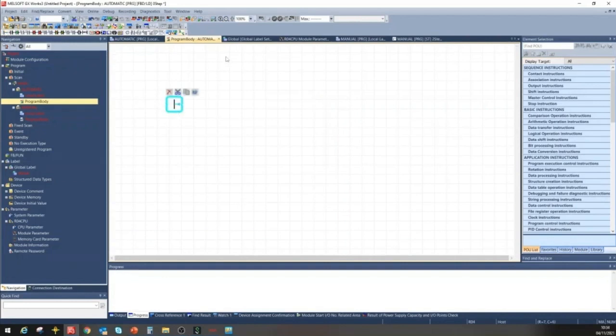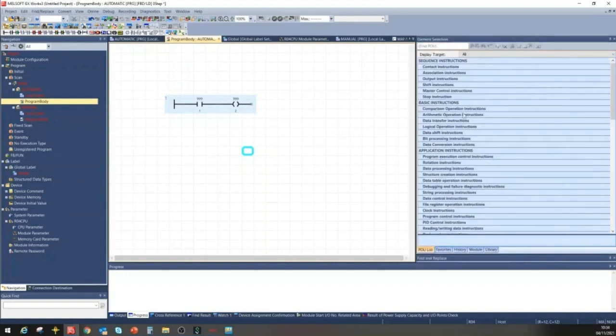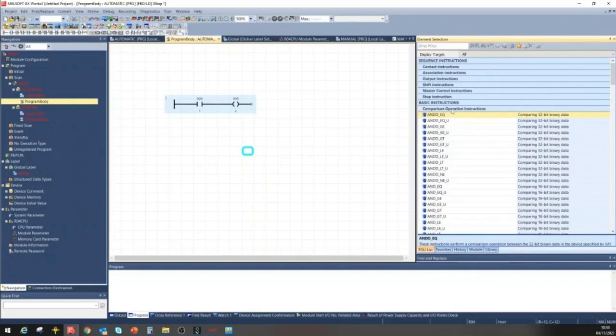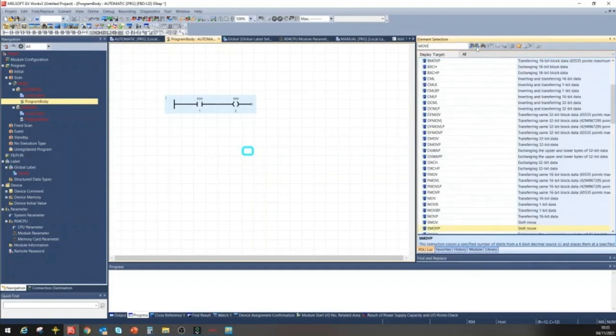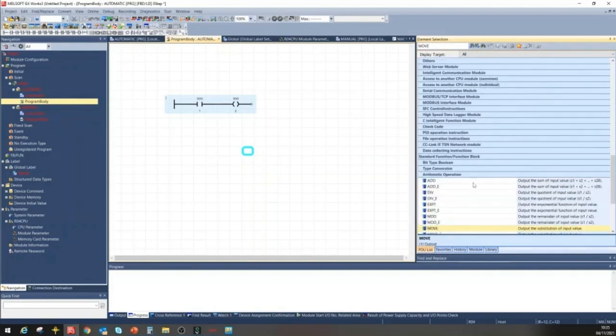Back in FBD, it presents, as we said, as a white analog sheet. Above, we find all the components typical for the FBD. So we can recreate our contacts and our coils. In this case, there are no assignments, so the question marks appear, and we go to the POU list and pick the integrated functions of the system, more or less basic. For example, basic instructions, comparison, operation instructions. We can choose a move. So we find the FBD blocks and the classic ladder rung for completeness.